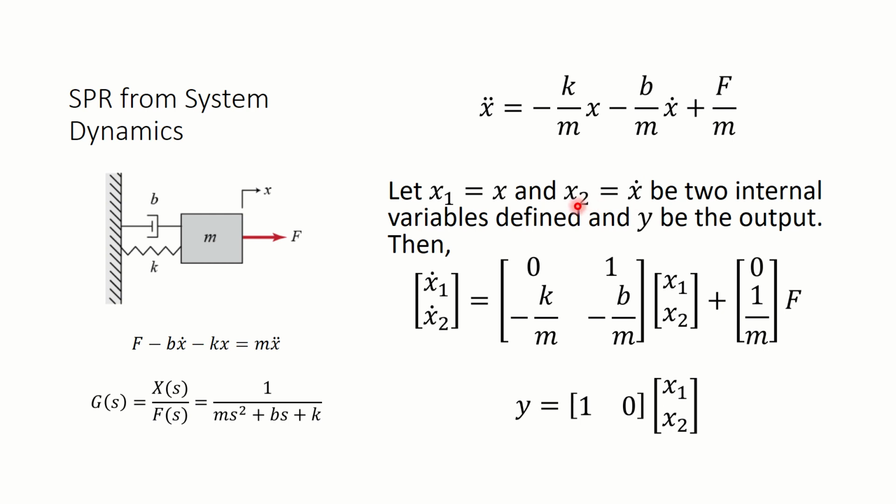You only have to keep in mind that for a second order system you have to define two states, and define them in such a way that the complete system description comes out. And when you define them in a bit different way than this simple approach, you come into a different derivation. You can try that while you are practicing and see what comes out. However, what I want to stress here is that all such definitions of states are equally valid.